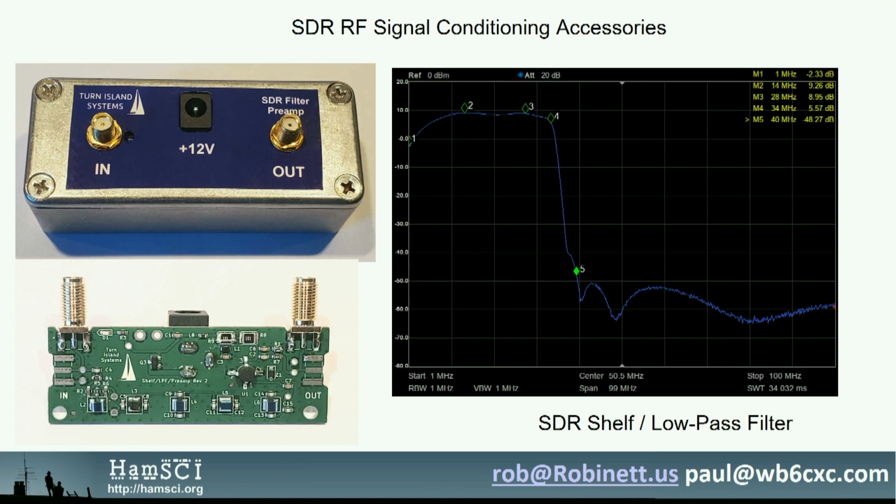That's why I think many people have had the experience of finding that their SDR is kind of deaf relative to their transceiver, especially on the higher frequencies. To address that problem, you need to put in a low noise amplifier ahead of the SDR, and Paul's device adds that feature.